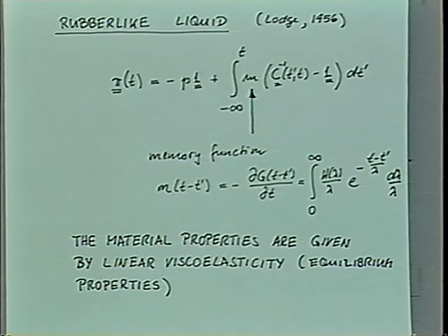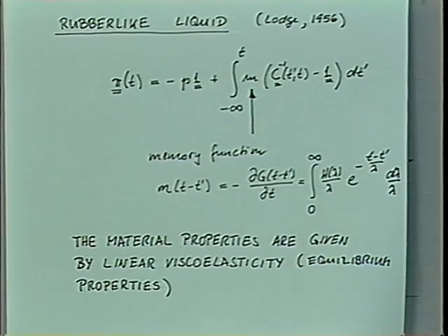So it's an intermediate model which we are going to discuss. And at those intermediate strains, up to maybe shear strains of 2 or 3, it gives predictions which agree very nicely with experiments. Also in extension, up to extensional strains of 3, it agrees very nicely with experiments. If you go to larger strains, then you have strain thinning coming in, and somehow you're moving away from equilibrium.